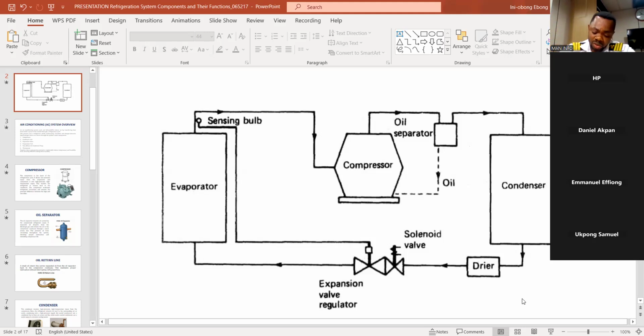If the capacitor is rated 50 µF, as µF means microfarad, they say plus or minus 5%, right? You need to calculate and know what is the 5% of 50. The reason why I do not want to go into troubleshooting today is that troubleshooting is kind of wide. Who can let me know the 5% of 50? The 5% of 50 is 2.5.